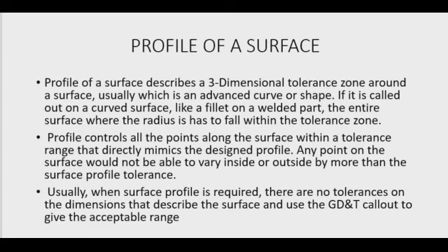Next we will move on to profile of a surface. Profile of a line is for 2D, meaning it is applicable to a 2D drawing, but profile of a surface is a 3D tolerance. It may be curved on a surface, like a fillet, like a welded part, or an entire surface with a radius having a certain range.